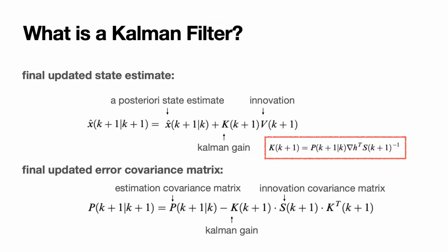The weighting factor, of course, is again the Kalman gain. It should be noted that using our raw pose data, like in the example, in our states with x and y and also with our heading is not optimal. And for real applications, quaternions should be used to further decrease computational complexity.